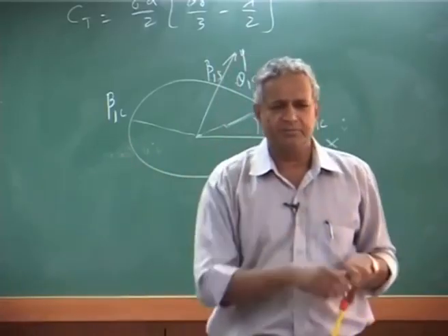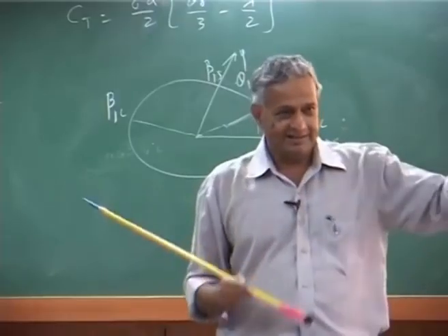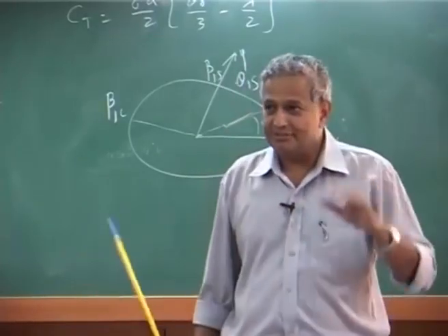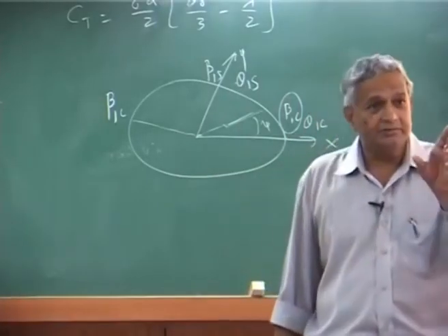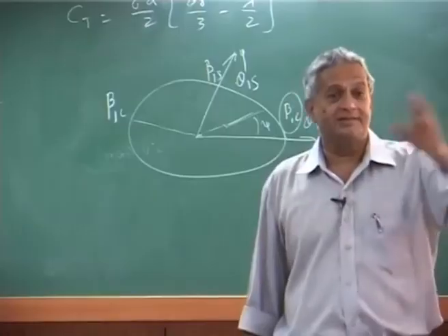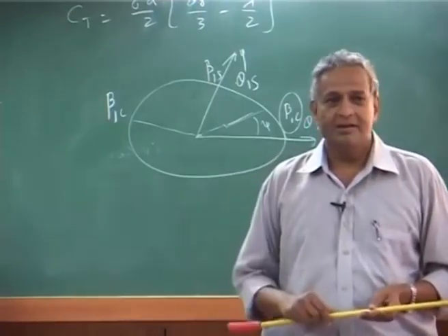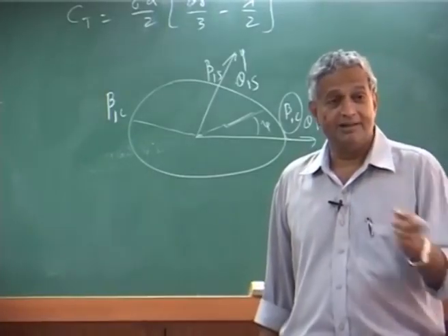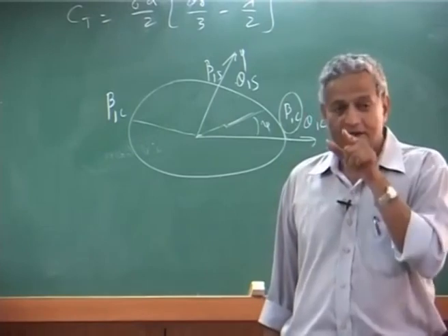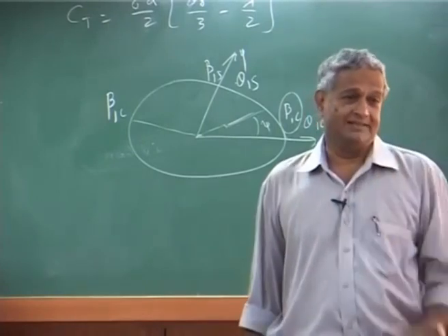The 90 phase shift comes because it is at resonance, because if you have studied a little bit more carefully your vibration part of the m x double dot problem, how the phase varies with frequency. All the phase curves, no matter what damping you have, will cross at omega over omega n equal to 1, at 90.